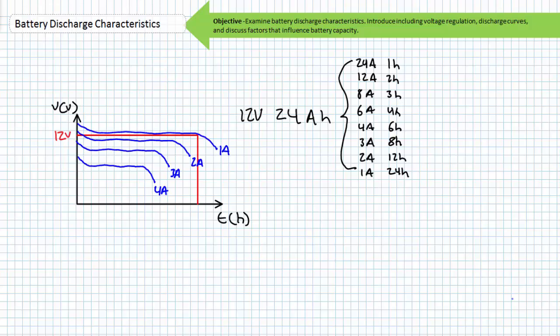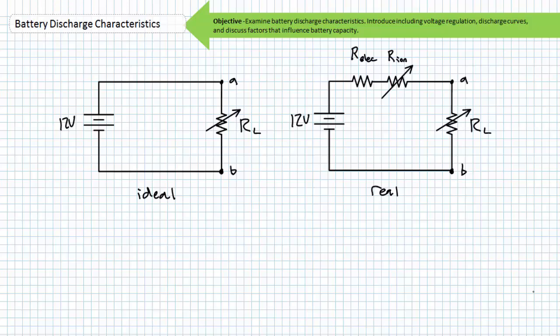This is a simplification only, and real batteries don't exhibit this behavior. The first brick wall reality throws in the way of this simplification is that batteries exhibit an internal resistance, sometimes called ESR or equivalent series resistance. The internal resistance comes from two sources. One, the relatively constant electrical resistance, and two, the varying ionic resistance, which is a function of electrolyte mobility and functional surface area. The internal resistance is a simplification of these effects into a single resistor in series with the battery and any electrical load attached to its accessible terminals.